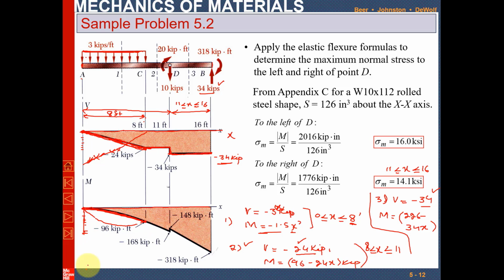I hope it's clear. Again I will repeat that you will look at the shear force diagram, and if this linear line is going downward, or the slope is decreasing, then in the bending moment the curve will be in clockwise direction.